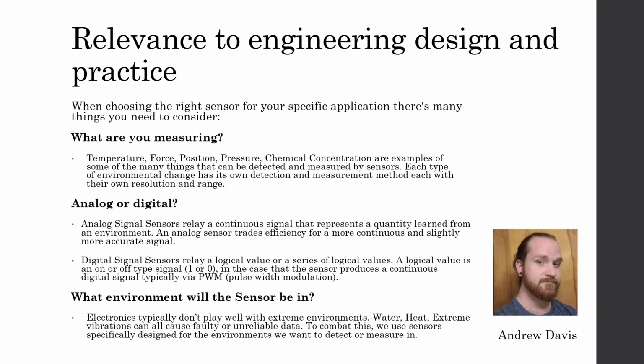Another thing we need to consider is what environment our sensors will be in. If we're trying to detect something in a high temperature environment, we want to use a high temperature sensor, something that can withstand the environmental issues. Electronics typically don't play well with extreme environments. Water, heat, and extreme vibrations can all cause faulty or unreliable data. To combat this, we use sensors designed specifically for what environment they will be in.